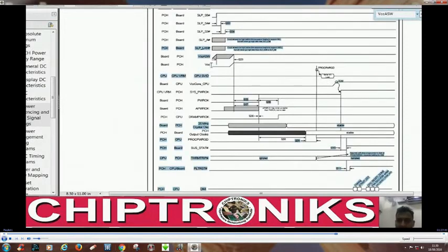After all these voltages are generated, we have seen that this IO controller generates VR on, and VR on is going to the core voltage regulators, and there is a very important point we have discussed in earlier class also, that in an Intel Series 6 chipset kind of board, the processor must be inserted in the notebook motherboard to turn on this notebook motherboard, whereas in boards having double bridge technology like north bridge and south bridge, we can turn on the notebook motherboard even without putting the processor.